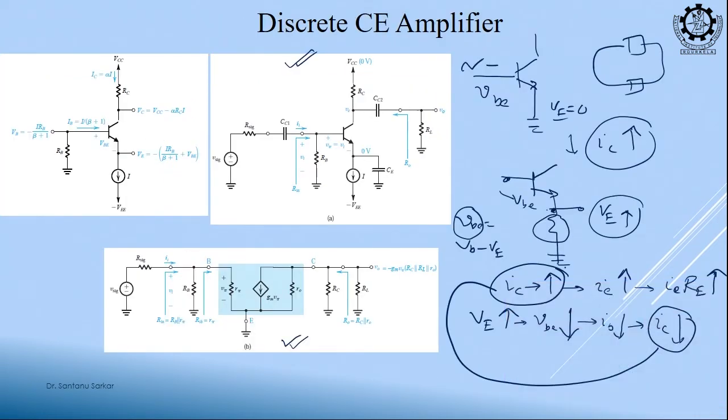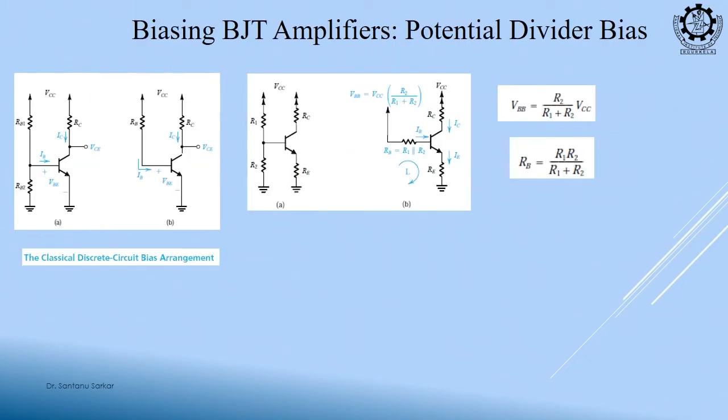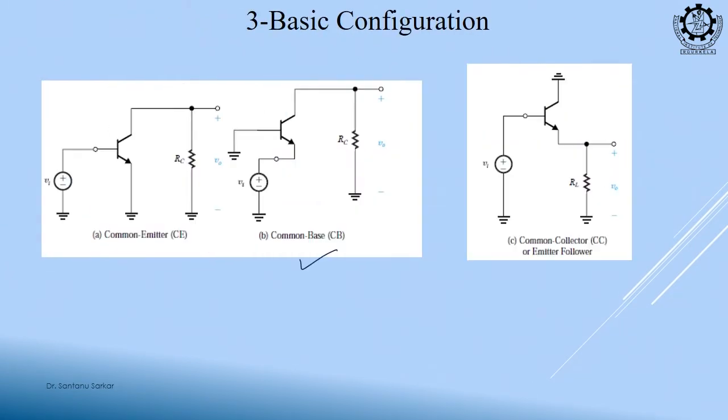So, always assume that you have to add all the DC bias on the AC circuit. The AC circuit is an equivalent circuit, you have to add all the DC bias. Maybe you have to add the potential divider here. This resistance is connected here, it will actually be here. This modification you should be confident to draw.